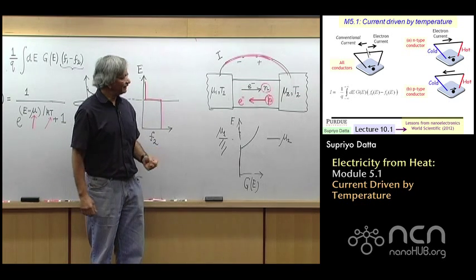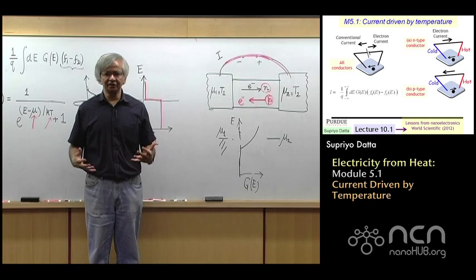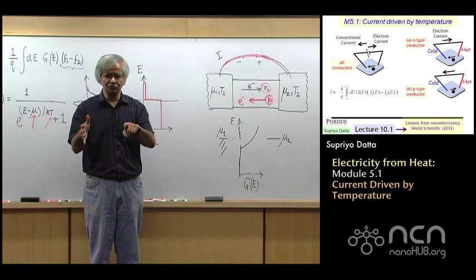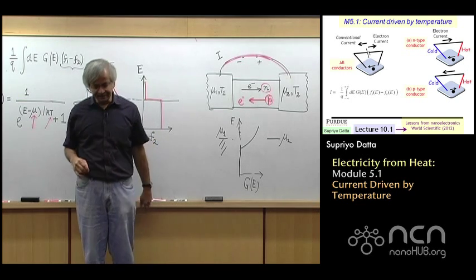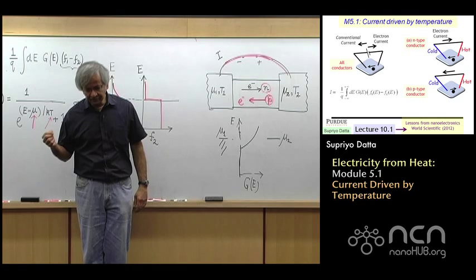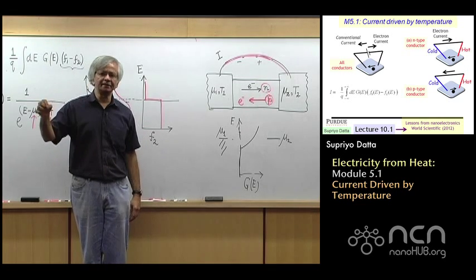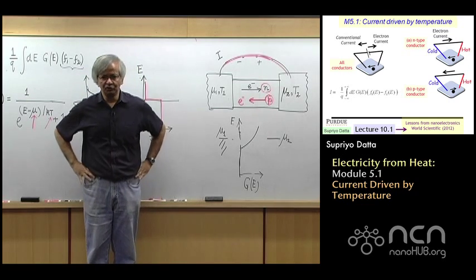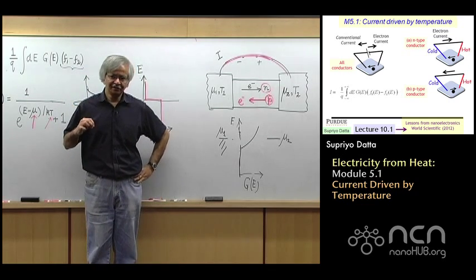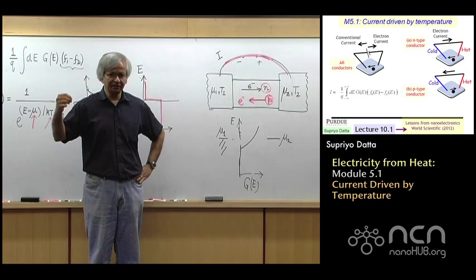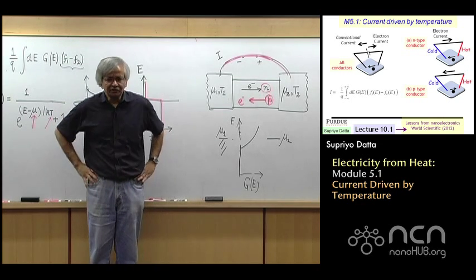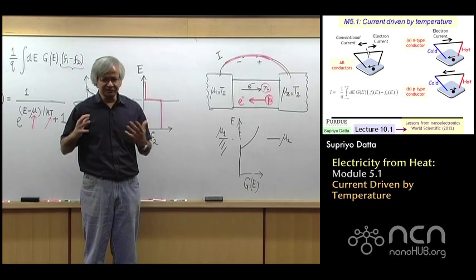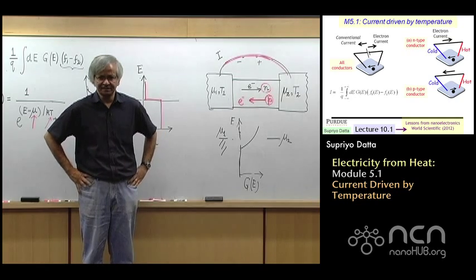But the point is that an effect that we measure in the laboratory, namely we put down two probes, one hot, one cold, look at which way the current flows, that's an experiment. And the result of an experiment cannot depend on what is conceptually convenient. Someone might find it easier to think in terms of holes, but that cannot change what we actually measure in the laboratory. So that's why this idea that because it's holes, the thing reverses is really an incomplete explanation at best.